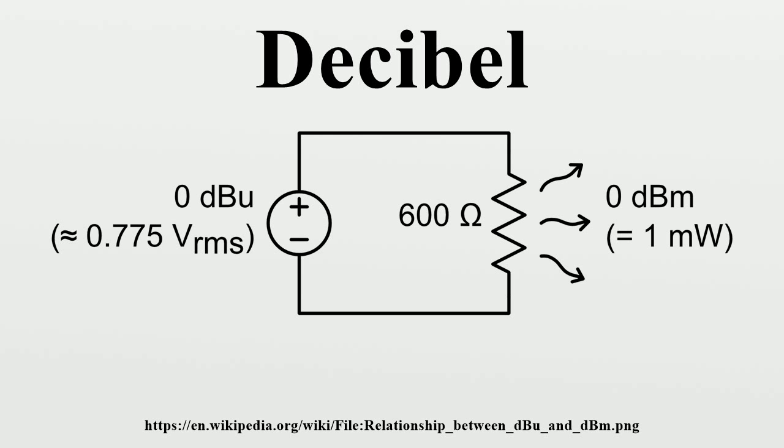A common source of confusion in using the decibel occurs when deciding about the use of 10*log or 20*log. In the original definition, it was a power measurement, and is employed in that context. The formulation 10*log should be used, as deci means 1/10. The user must be clear whether the quantity expressed is power or amplitude.